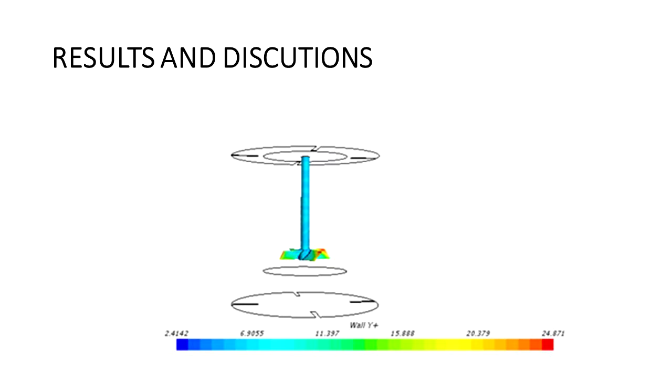To make sure the mesh was correctly done, we did a Y plus wall tool, in which you can see here that the impeller tends to have a small wall Y plus, which means there is a high number of cells. Still, there are some important zones in the plates where there's a very big wall Y plus number. This means that there is not as big an amount of cells as you would like.